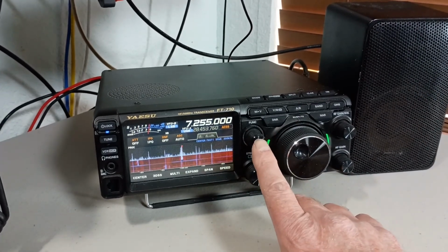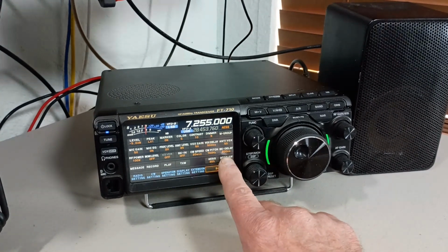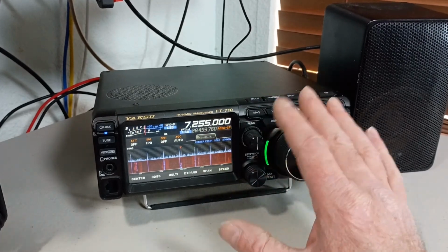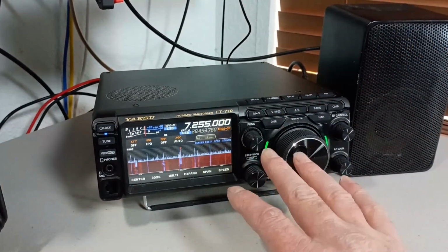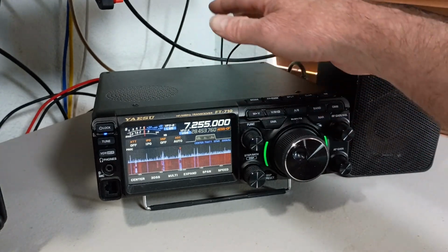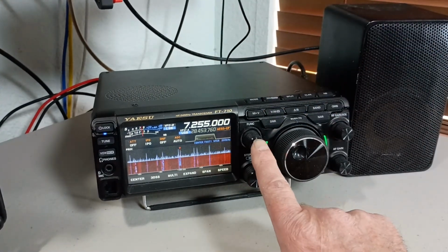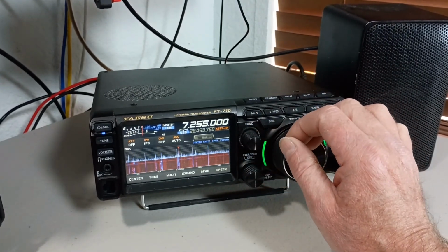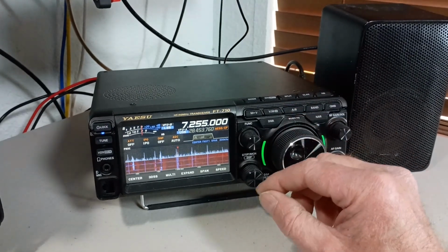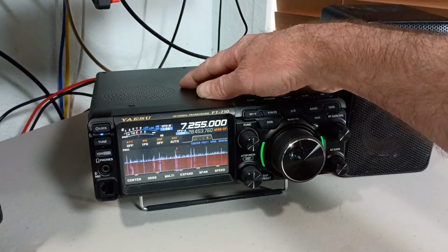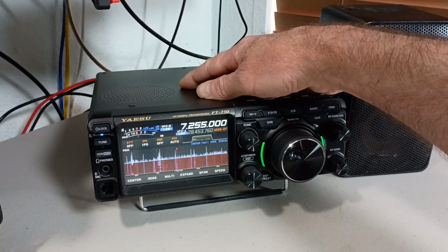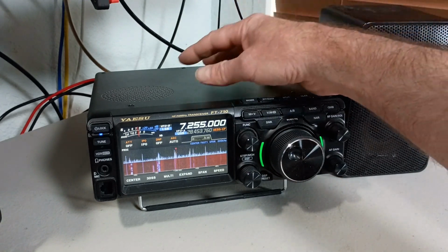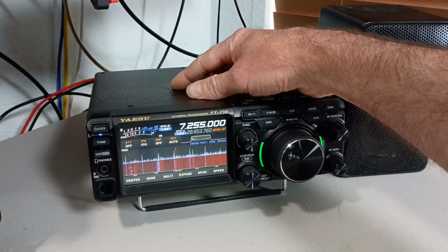And that's not the case, because I can show you here that I've already got the low cut filter set at 700 hertz. The way that works is when the AESS is on, you can choose either a 1000 hertz filter or a 700 hertz filter. These are low pass filters. So at the 700 hertz setting, audio that's 700 hertz or less will go to the internal speaker in the radio. And when you switch it to 1000 hertz, audio that's 1000 hertz or less will go to the radio.